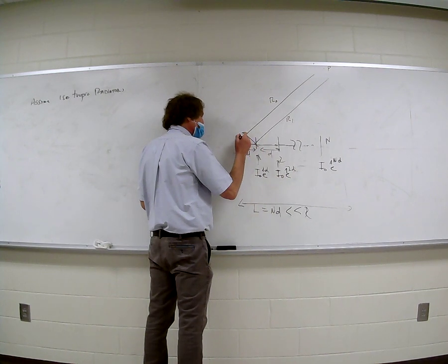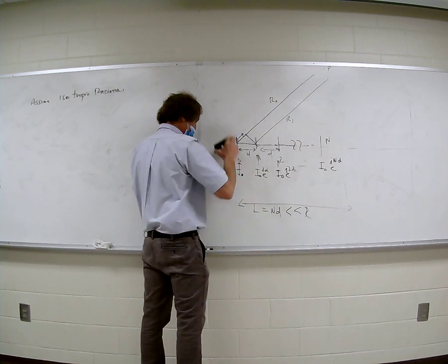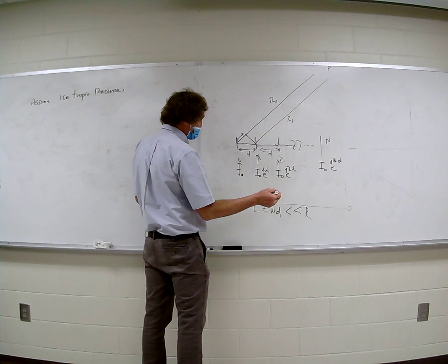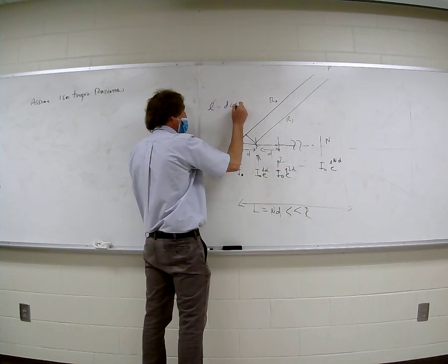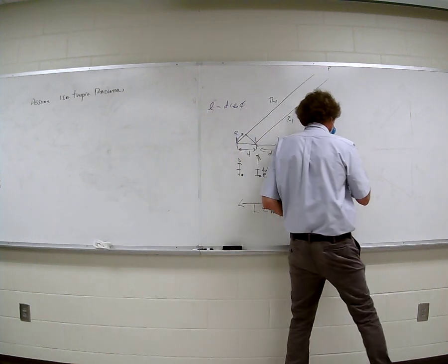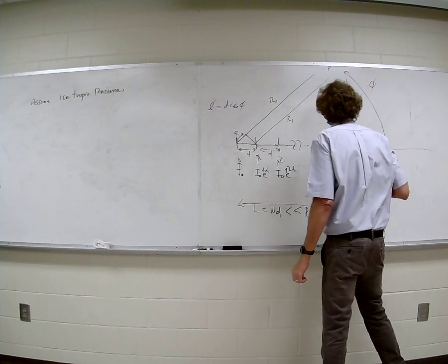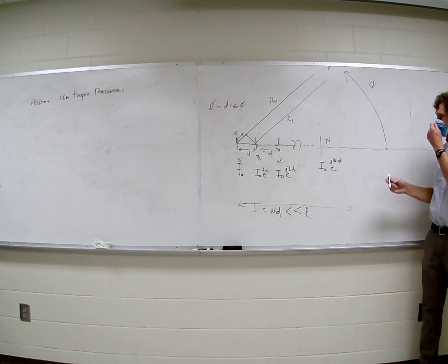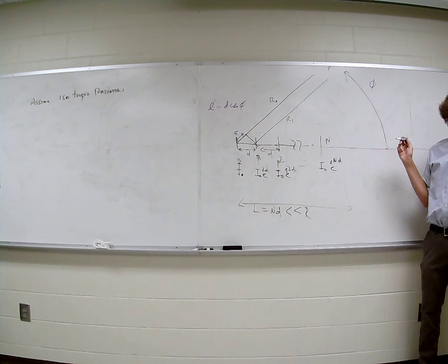Can everybody see this? So this distance here, I won't call it d. Let me call it L, right there. This length L would actually be d times the cosine of theta. And I'm going to just show you what theta is. Theta is going to be the angle that radius vector r makes with the axis of the antenna. All with me? I'm doing it this way for a reason. It'll make it a lot easier. And also be consistent with Wentworth's order.